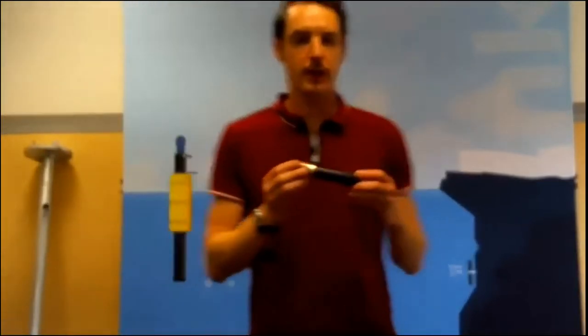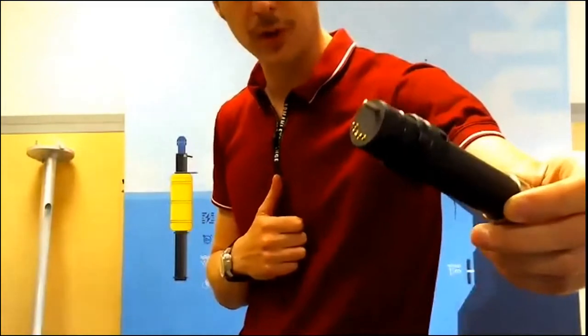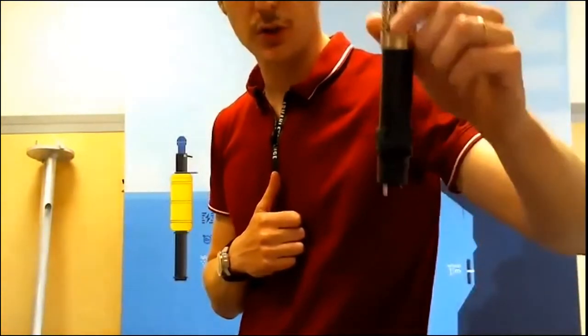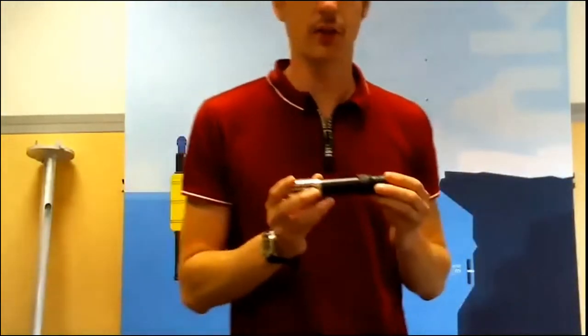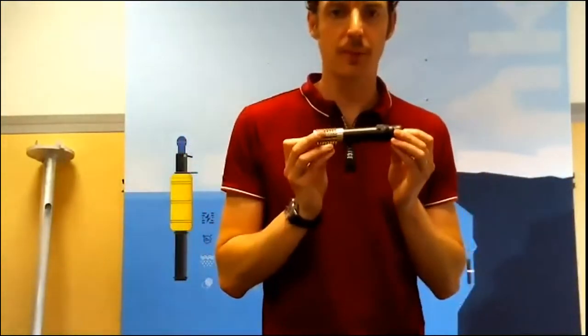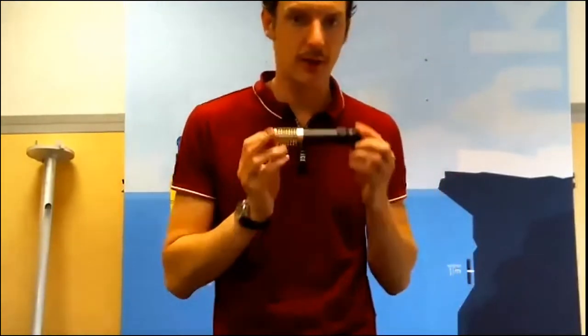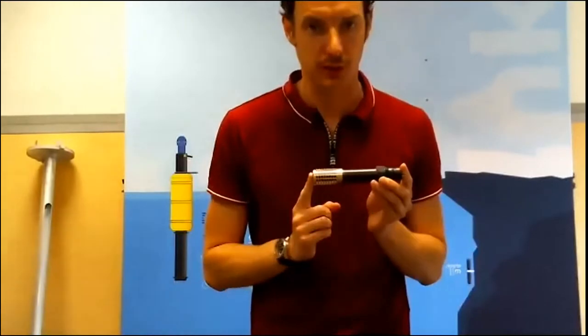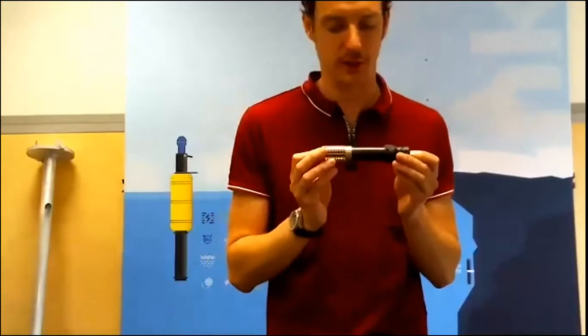Most of the brain is actually inside the digital sensors. The digital sensors are real plug-and-play sensors. We have designed our own connection type with coded pin in order to ensure the 250 meters depth ratio. Each sensor stores its calibration inside, which means that you can actually calibrate the sensor separately from the sonde. And this is pretty interesting. You don't need the sonde in order to calibrate the sensor.